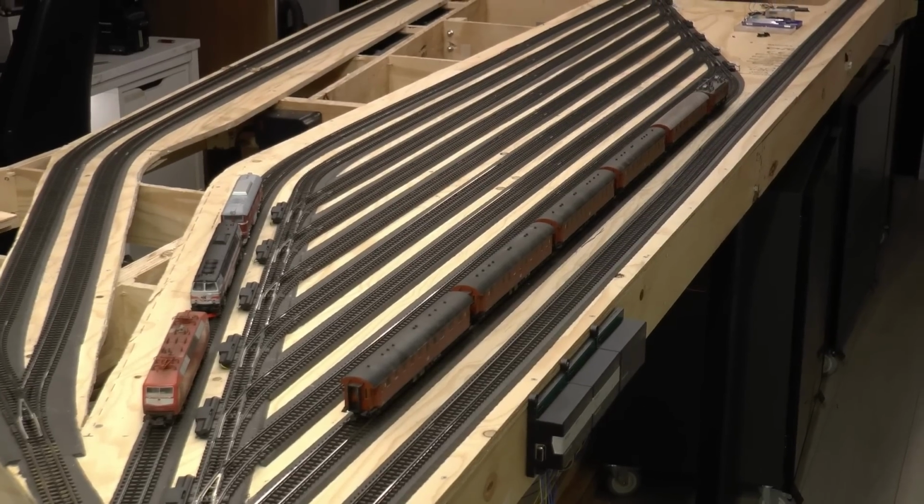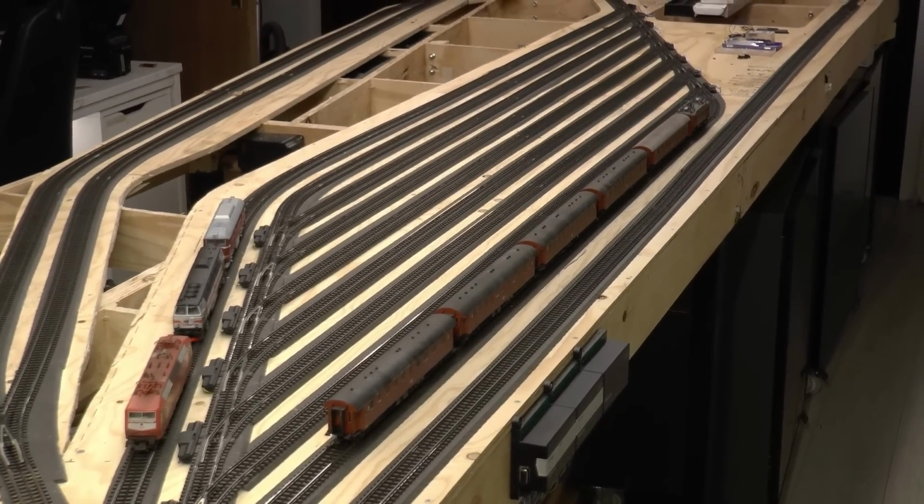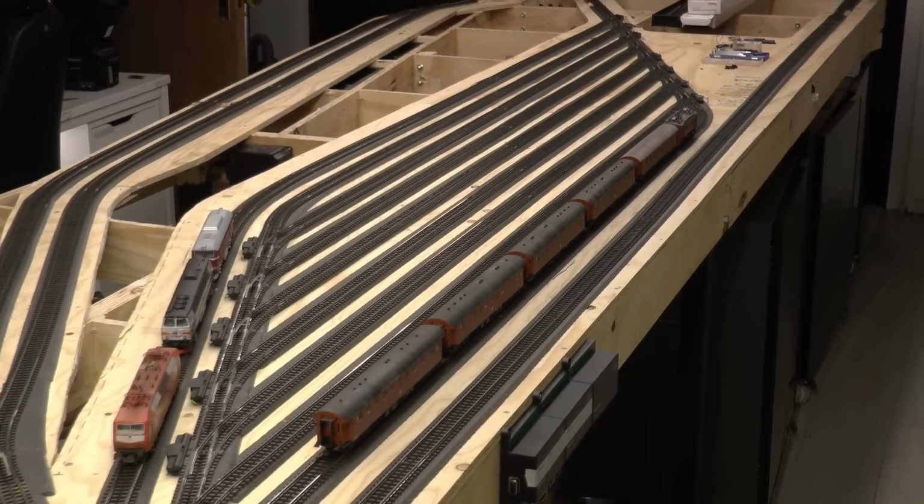The idea was to save sensor inputs and reduce cabling, which is initially a good idea, but it turned out that the trains were constantly standing and waiting for the next block to free up, since all the blocks were busy all the time. So that's a mistake I can tell you to avoid. Stick to your defined length of block sections when splitting the line into blocks.